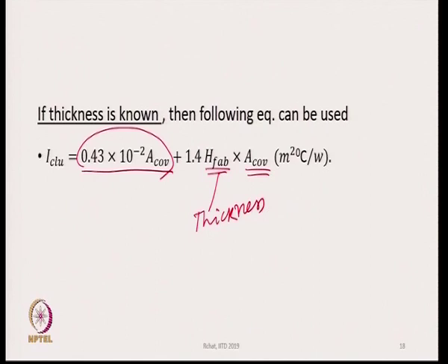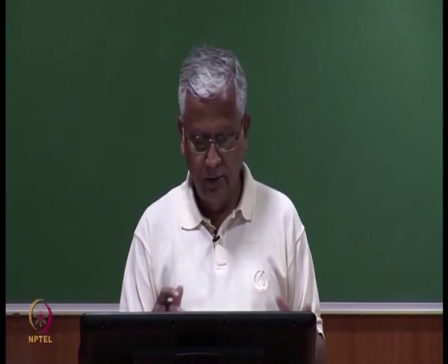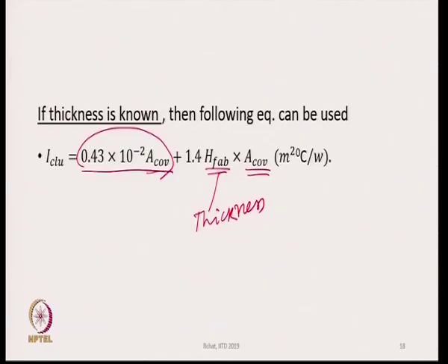Thickness has to be measured following a standard. The standard states that so much pressure has to be applied, and then we measure the thickness value. From the thickness value and the percentage area that the garment is going to cover, we can find out the insulation value of a garment made from that particular fabric.